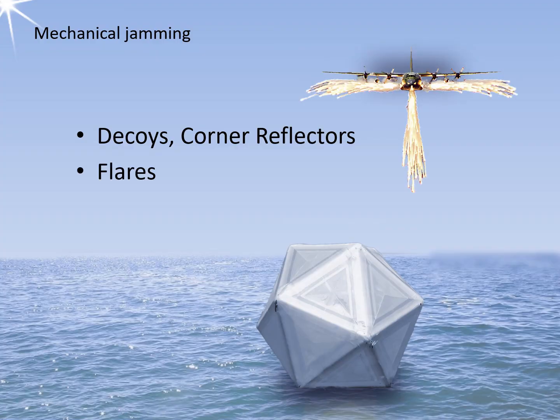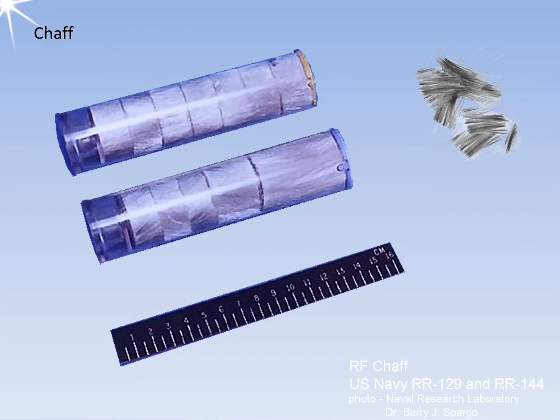Flares are infrared countermeasures that protect target platforms against heat-seeking missile threats. Chaff is a radar countermeasure in which a cloud of small, thin pieces of aluminum, metallized fiberglass, or metallized plastic is distributed, creating additional interfering echo signals on the screen. Half-wave dipoles are especially effective as radar reflectors. Typically, to counter a 10 GHz radar, the dimensions of the chaff dipoles would be 0.6 inches long, 0.01 inches wide, and 0.001 inches thick.